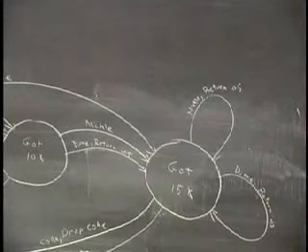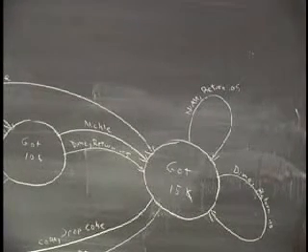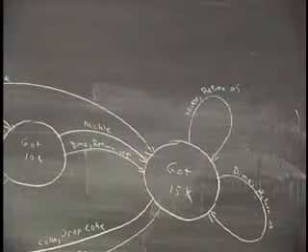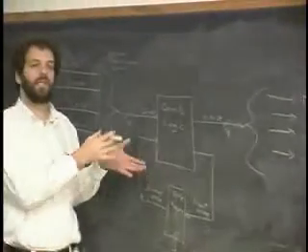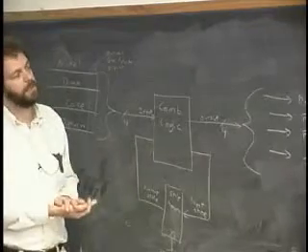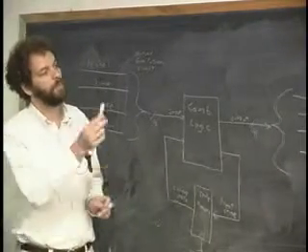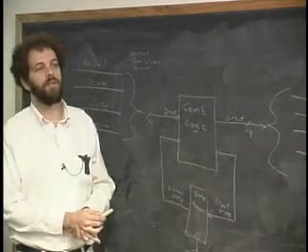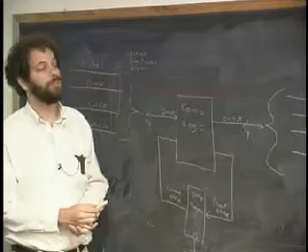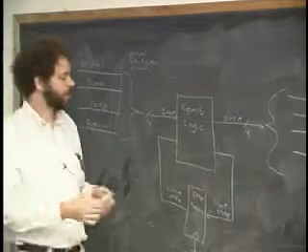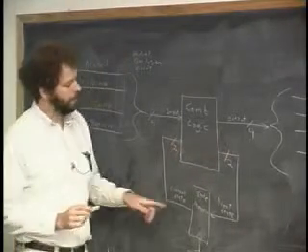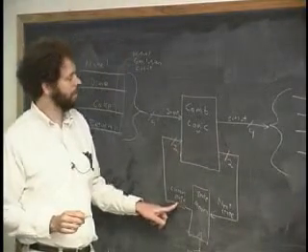And what it says is that there are 4 states, and that there are 4 inputs, which are mutually exclusive in this case, and 4 different outputs that this thing may have. And what's neat about it is that now we can go ahead and encode this in hardware. Now, how many bits of storage do I need to remember which of those 4 states I'm in? There's 4 possible states, so how many bits do I need? 2, right, because 2 to the 2 is 4. So there are 4 combinations. So I know that I only need 2 bits here and 2 bits here. And this thing will keep track at any given time what the current state is.